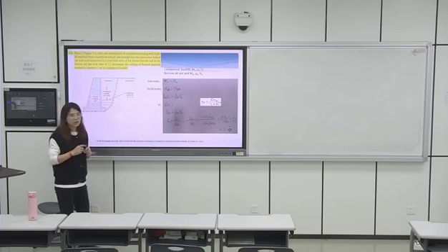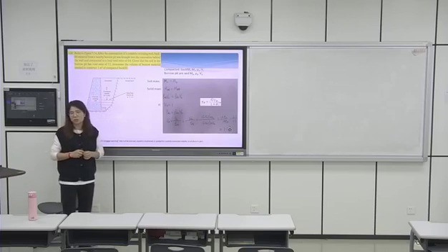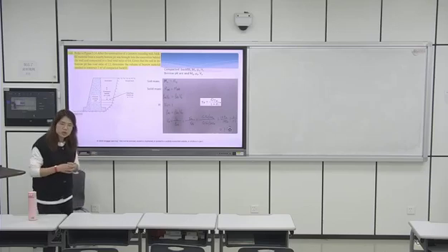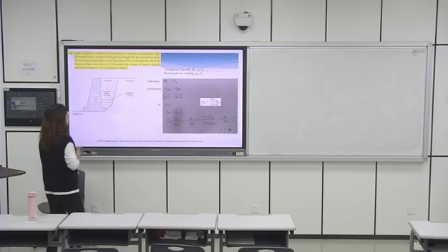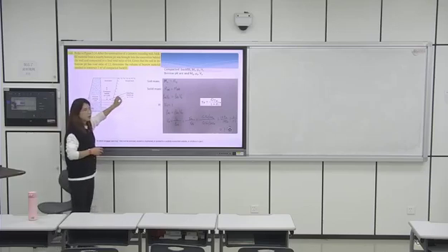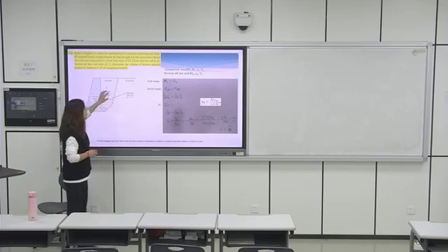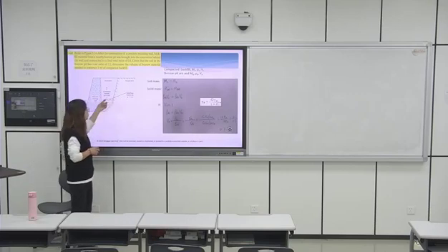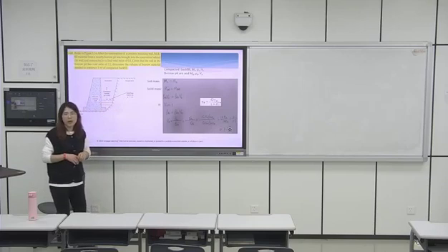The only thing we changed in here is just the volume. The volume changed just because the void ratio changed. We compacted very loose soil in here to dense soil here, because we compacted it, the void ratio reduced to 0.8. This is an important thing, right?